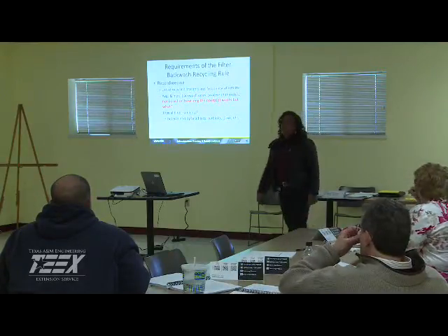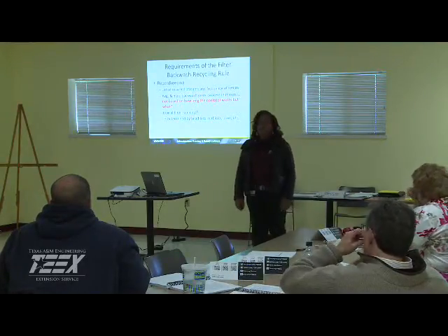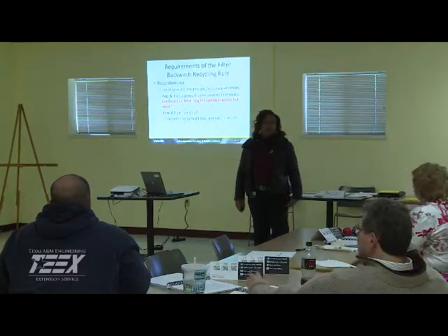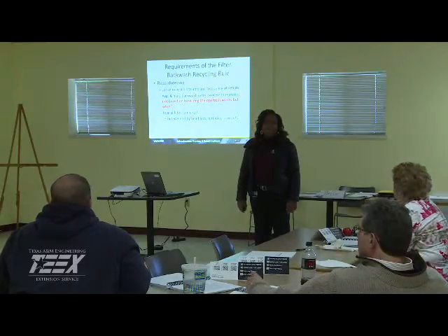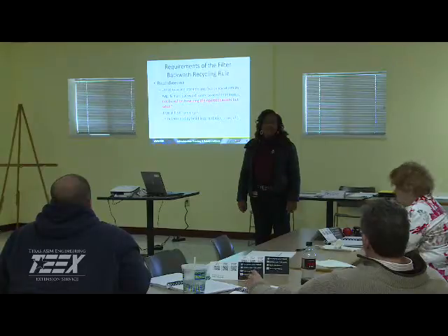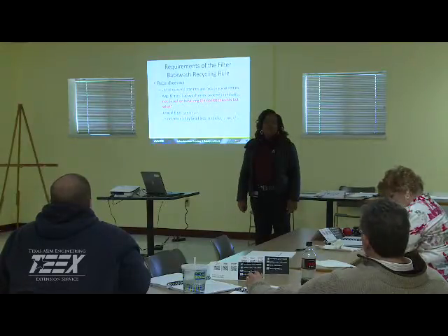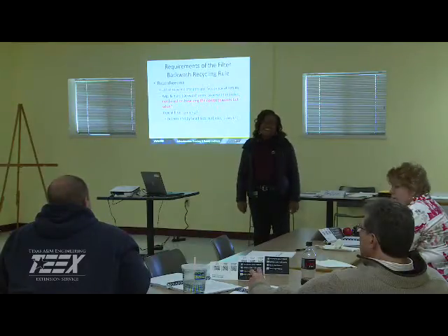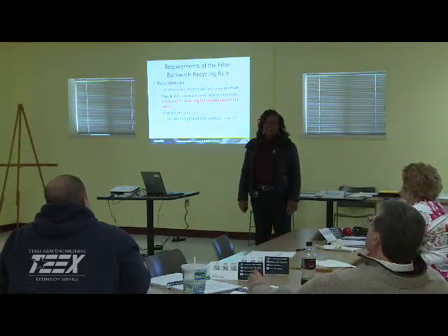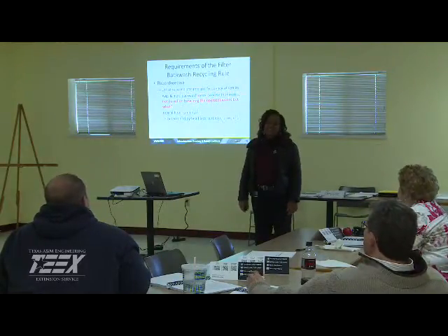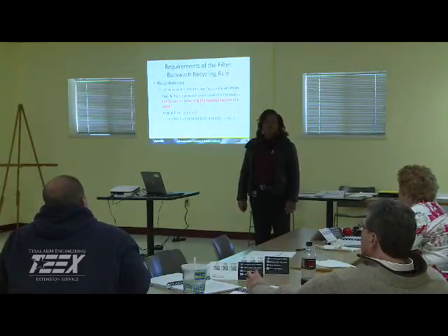Is there any telltale sign when I need to backwash? Finished water contaminant levels start maybe going a little higher than they normally are. Finished water turbidity samples. Head loss.